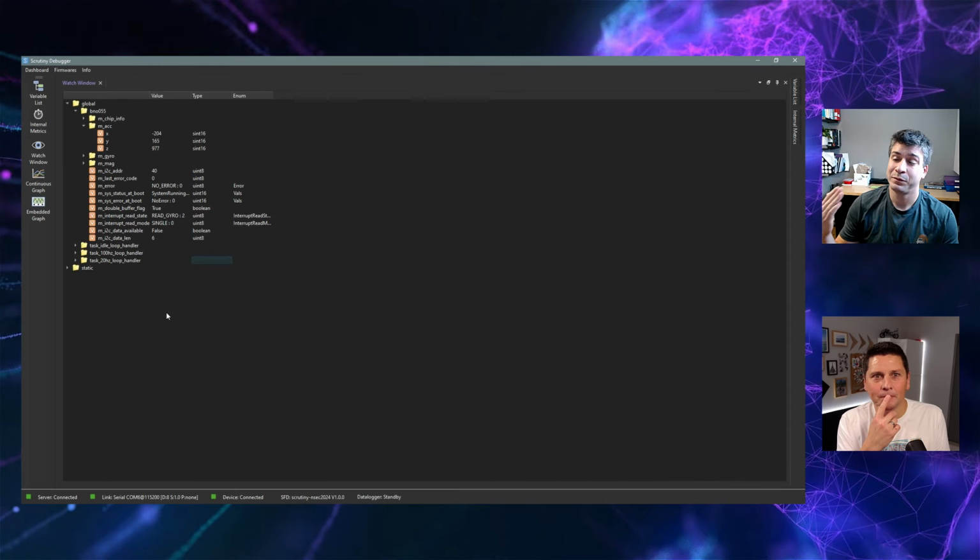So now there's a little problem that comes when you do that. Okay, tell me. Each time you modify your firmware and you make a new firmware revision, variables will move. Oh, okay. Like if you put a class into a namespace, boom, everything changes, and then the variable is not available anymore at the same location, because every variable has a location, and we see it here. That's the path to the variable.